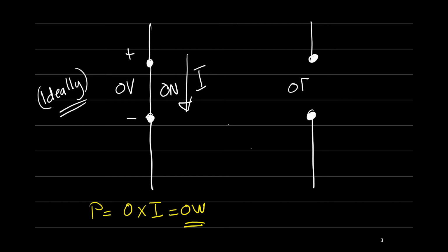Let's have a look when the switch is off. You will find that when the switch is off, this means it's an open circuit, zero current, and we have a specific voltage across this transistor or this switch. If you calculate the power, then the power will be the current times the voltage again. So it's zero current times any value, it will be 0 watts. Again, this is an ideal switch and also will have 0 power losses when it's off.